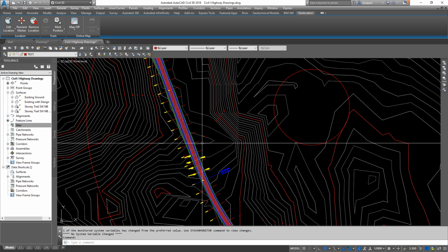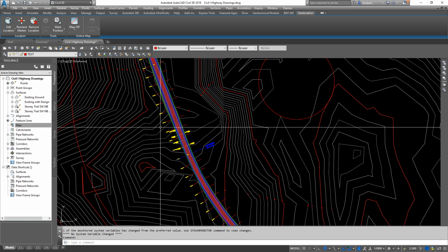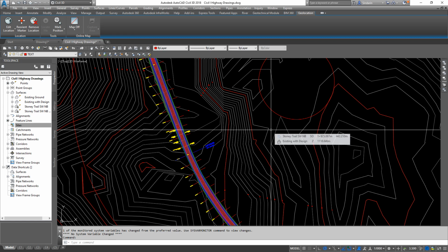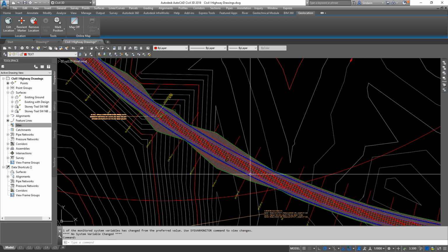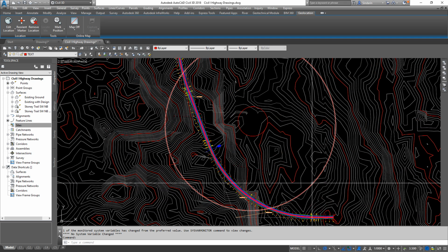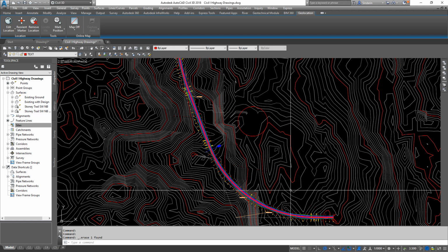Now, we need to ensure that water from our road makes its way into the pond. Now, that would involve 2 or 3 more sets of grading objects, 2 or 3 more sets of calculations, 2 or 3 more sets of layers of grading that can possibly go wrong. There's my original circle. So we don't want to really add too much more to our pond. We'd have to design a ditch. We'd have to design an inlet into the pond. We'd have to design an outlet from the ditch into our new ditch.